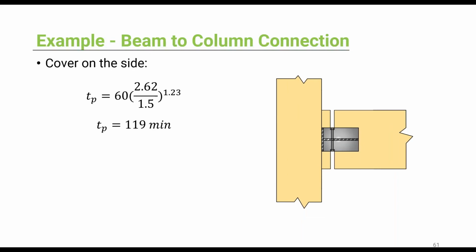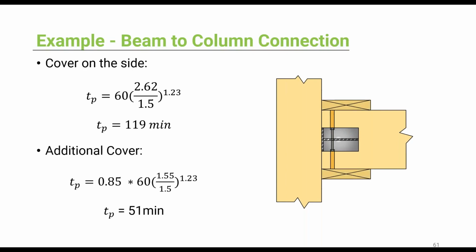We also have to check if there's cover needed on the sides of the connector. After you plug in the holes for the bolt, we see that the wood cover on the side of the connector is not enough for 120 minutes. So you have to do the calculations again, and you have to add extra wood cover.